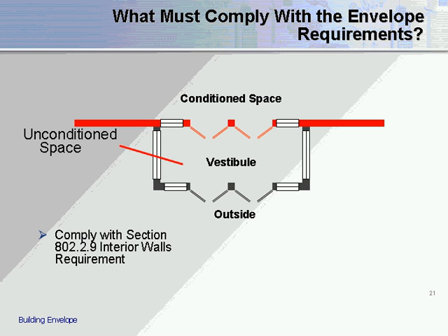If we look at the particular example that we have up, the red wall on here is considered the wall between the conditioned space and the outside. So the red wall would be considered our exterior wall. The IECC essentially says that exterior doors must have vestibules on them. So the door that we're looking at, the entrance door here and here, would be a door between a conditioned space and the outside until we get the vestibule on that.